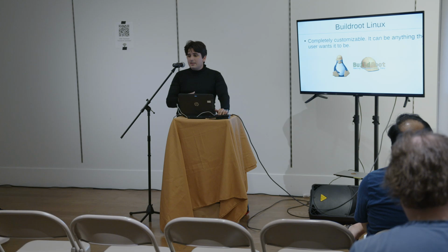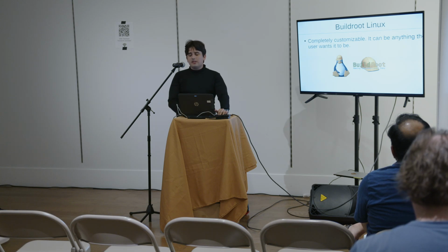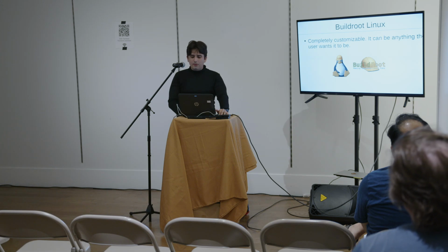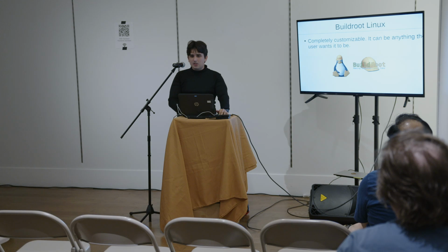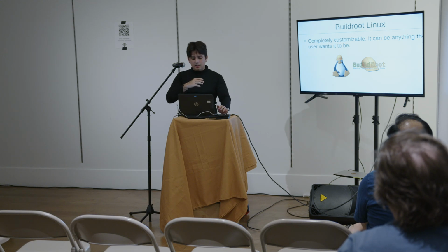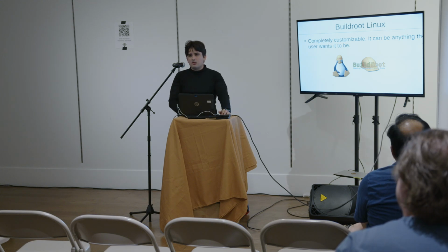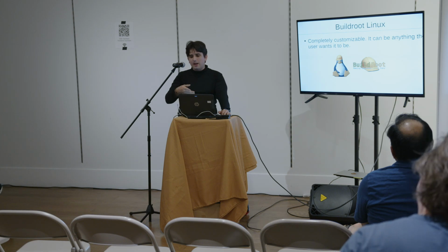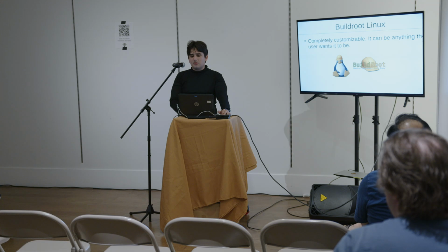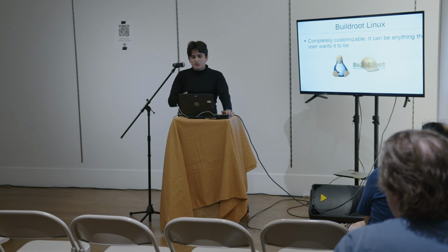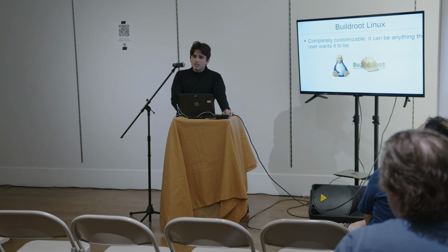So we needed to make a new custom image for this device. And we had many options. Actually, one of our first custom images was an Ubuntu distribution. We took the source code and we recompiled the kernel to accommodate our different device tree source. However, you don't really want to use a common distribution like Ubuntu on a platform like this.